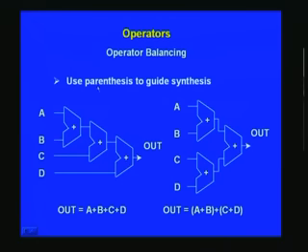And we have one more thing before we wind this up. Let us say we want to have an arithmetic operation done. Let us say a plus b plus c plus d is what we want to compute. If you put this condition here, the synthesis tool will map it like this. It will put 3 adders. The a plus b result will be available here, then this will in turn be added with c, and that will appear here and get added in the final last adder, and finally the output will be this.